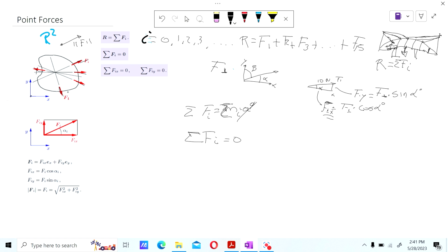It's still in the same place where the bridge was located, but there are some internal forces, and if the force is too high, you can cause fracture or deformation that can damage it, and then maintenance has to be done. But the bridge is not going to be moving around like a car would when you apply acceleration to it. So that's the second thing. The first thing is to compute the total amount of force. The second thing is to know that in equilibrium, all the forces need to be equal to zero.